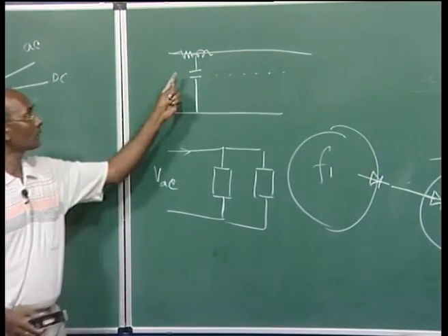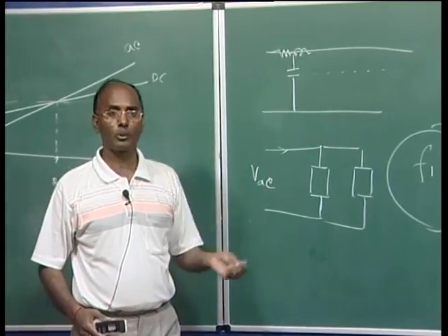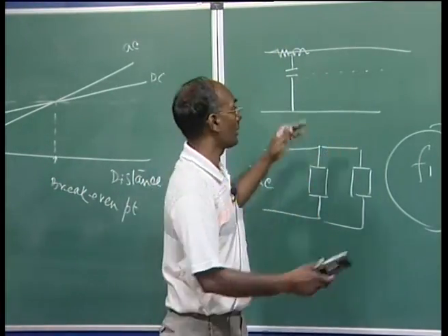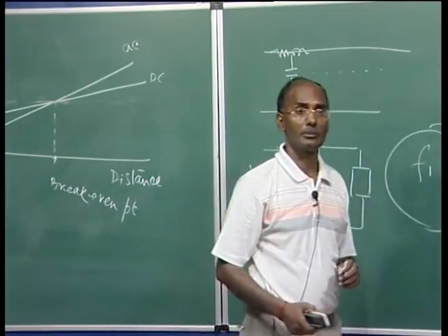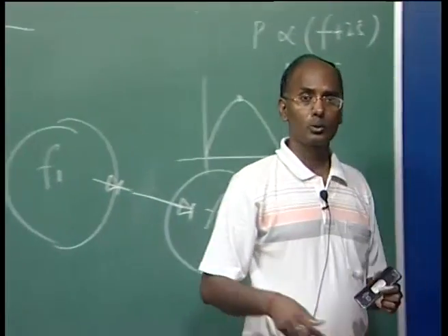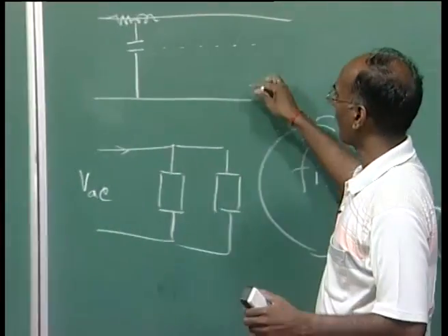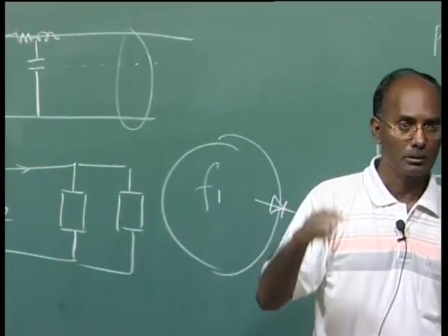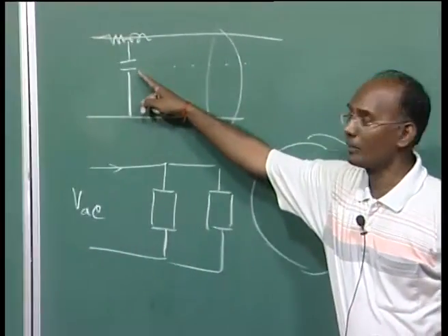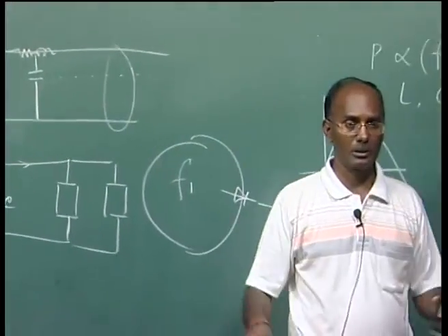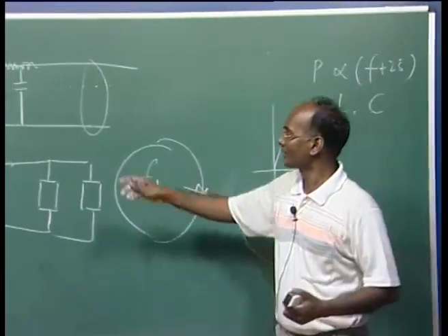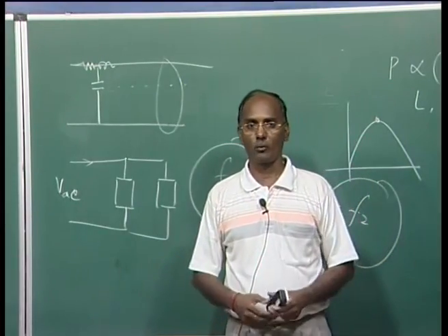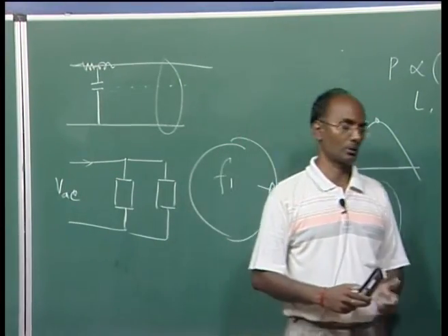What happens due to this capacitance? We have to compensate it, otherwise the voltage in the middle of the line will be very high compared to the sending and receiving ends, and there will be flashover. So if the line is very long, we have to use some compensating device in the intermediate, so that we can absorb some of the reactive power generated by these distributed capacitors. However, in DC this concept is not there, and thereby no compensation is required. We can operate the line very smoothly.